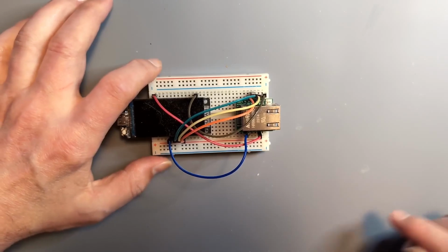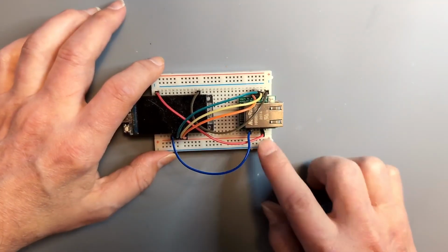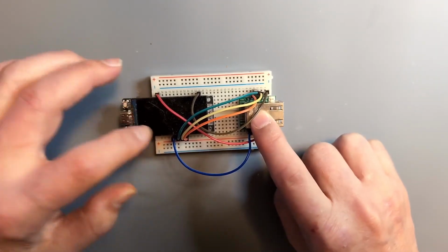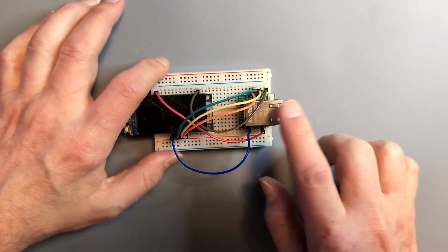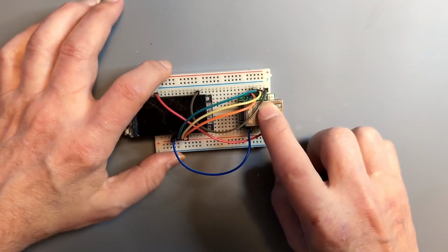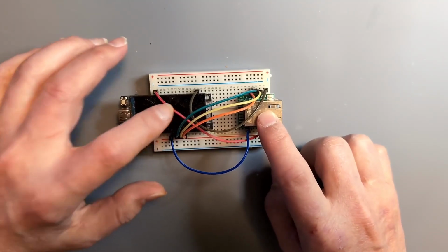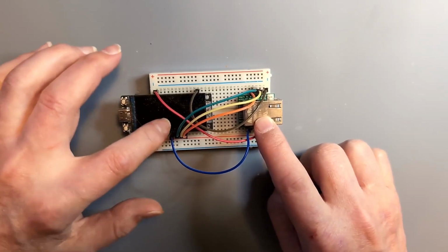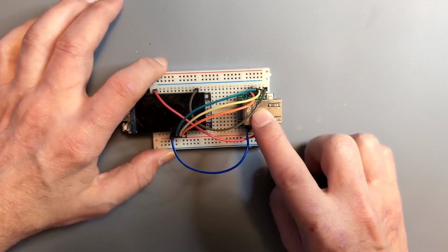Okay, let's take a look at the construction. What I have here is various sets of jumper wires that are jumpering the W5500 over to the T-Display, and that will allow the W5500 to communicate with it. The W5500 does run on SPI, and the LilyGo T-Display S3 does have two SPI ports. Unfortunately, one of them is already tied up with the display module. So let's take a look at the IDE and I'll show you how the program works.